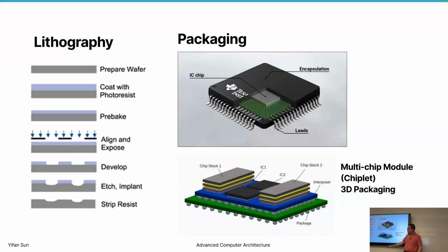So we say chips, there are three tiers of network: in-chip network, in-package network, and off-package network. Each layer, the lower the layer, consumes more energy and is slower, right? So the interposer provides a faster network than going off chip, going to the PCIe bus or something else, right? That's why this technology is so important.